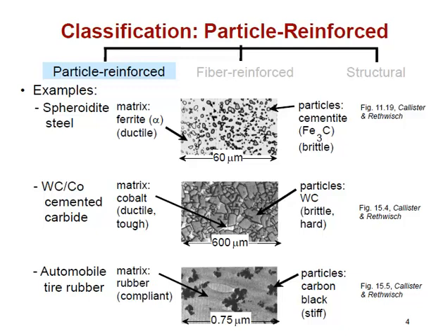And the last one is a polymer in polymer particulate reinforcement. This is carbon black in rubber, very essential for automotive tires and many different rubber applications. In addition to being a mechanical strengthener, those carbon particles also contribute to good photocorrosion resistance. They're excellent ultraviolet absorbers, and so when they're added to a polymer used outdoors in a weathering application, they give it quite a bit of resistance to photolysis and photooxidation.